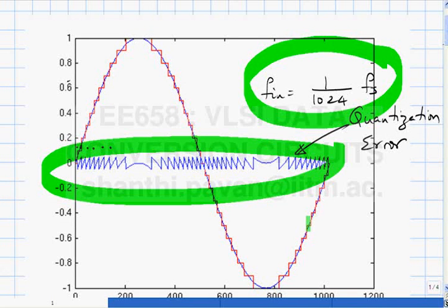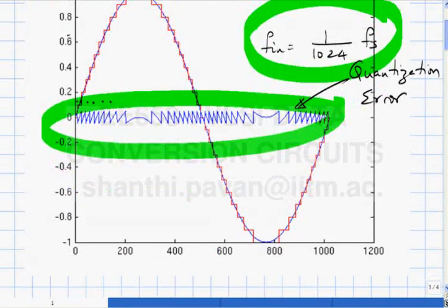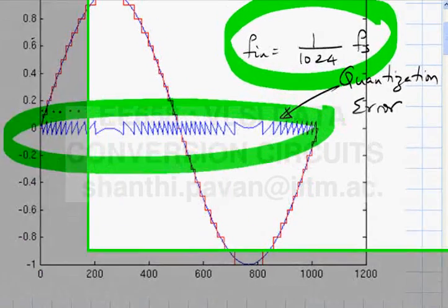All that I'm saying is that if the input frequency is very, very small compared to the sampling rate, which is certainly true in this particular example, then the coefficients of the discrete Fourier series that you get when you expand this discrete time periodic sequence will be very similar to the coefficients you get from the continuous time Fourier series, assuming this is purely continuous time.